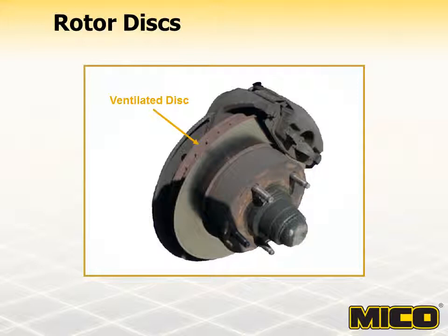The rotor disc should not have an overly smooth finish because the disc is used to wear in new linings. This is called burnishing. A well-burnished disc will look like it has a mirror finish. This indicates that the lining and disc are mating well and that friction levels are quite high. A new unburnished lining and disc may have friction levels as low as 50% of a fully burnished lining and disc.